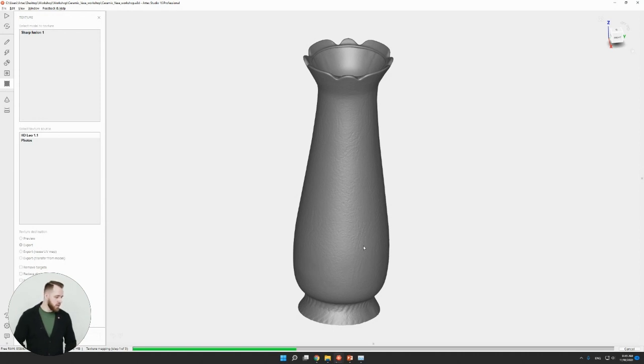We can also check the settings that I used. I used export mode, which is the default mode for texturing. And also I have the in-paint missing texture setting turned on, which means if there are any areas which we kind of missed or skipped with a texture camera, this area will be filled with the texture from the surrounding areas. So this algorithm evaluates the texture from the surrounding areas and fills all the void with something that looks like the surrounding area. For this model, I don't think we'll have any of these areas at all, but just in case, let's select it.